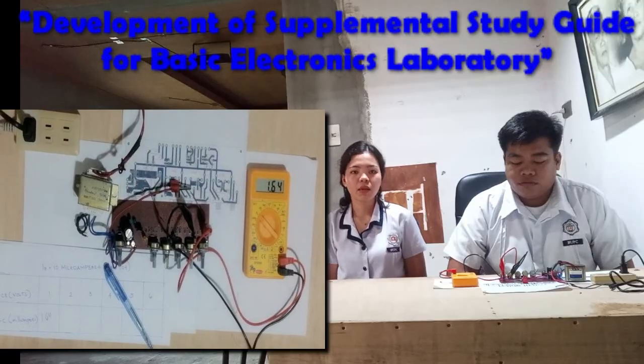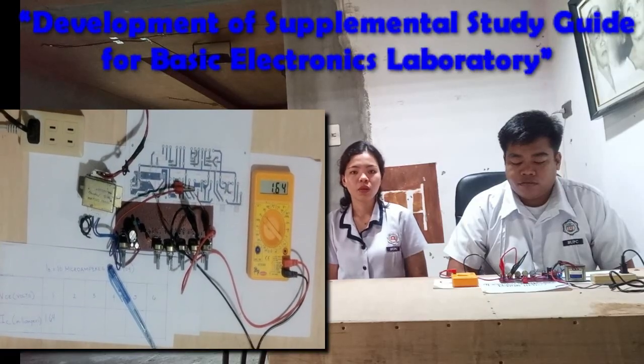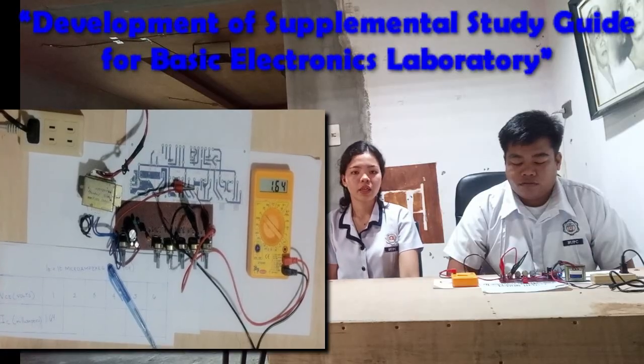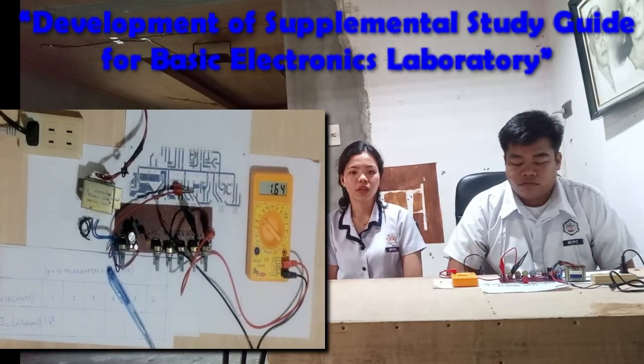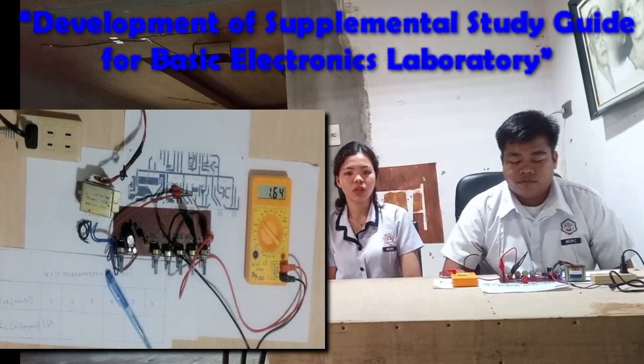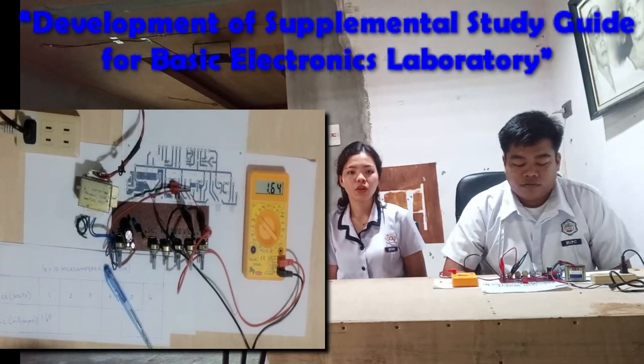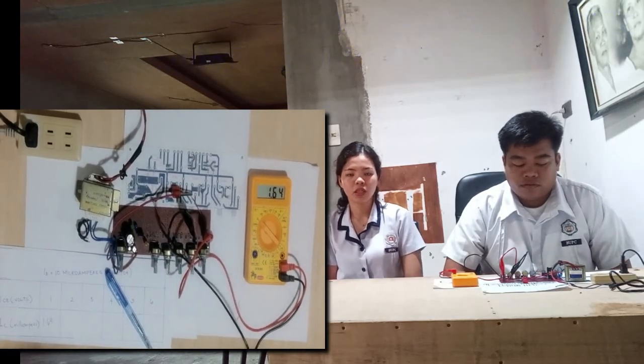When you complete the table in figure 3-4, we will have a permanent record of collector current values over a range of collector to emitter voltage values when base current is held constant at 10 microamperes.